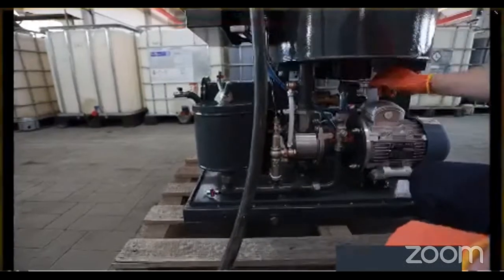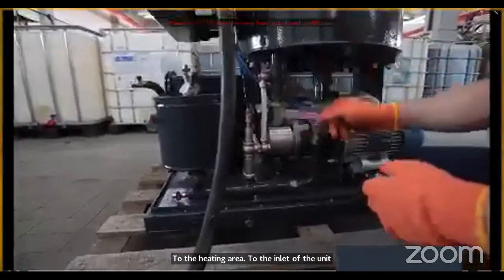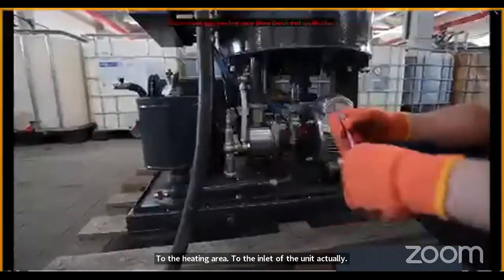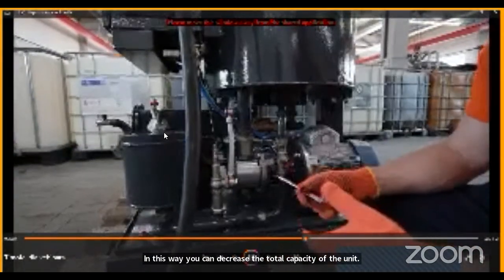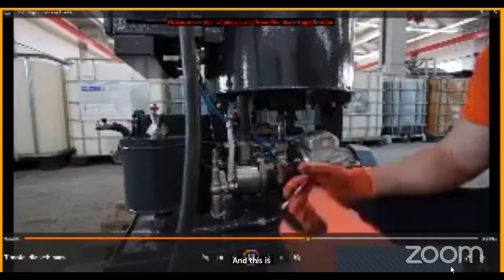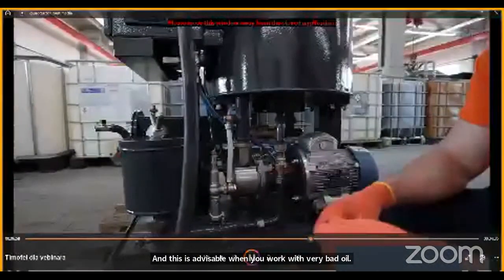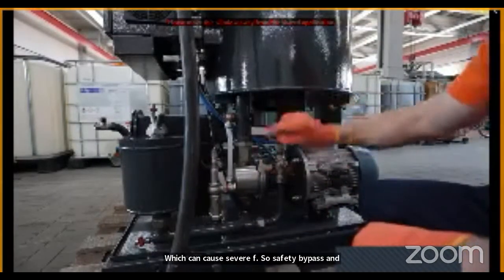To the heating area, to the inlet of the unit actually. In this way you can decrease the total capacity of the unit, and this is advisable when you work with very wet oil, which can cause severe foaming. So, safety bypass and capacity control bypass.